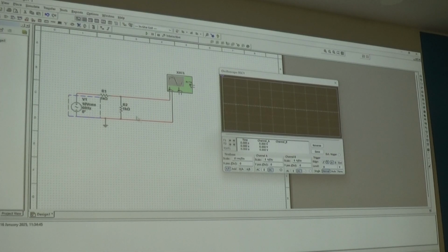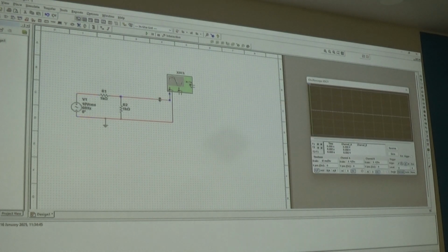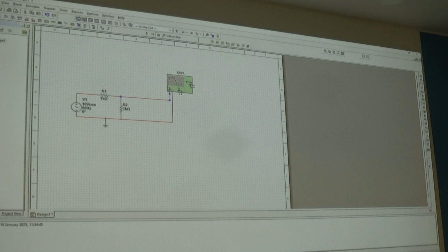So now what I can do here is if I increase the size of R1, I'm going to drop more volts across R1. So R1 should control, or should reduce the amplitude of that sine wave according to the value that I assign to it. Let's do something else now which is also a bit clever. I'm going to delete, shut it down for a minute. I'm going to delete these here and do something which is very, very common when you do AC analysis.